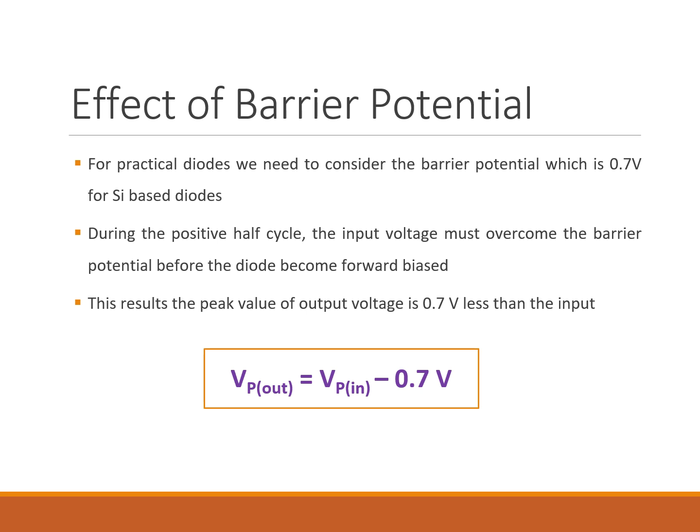And this matters because in low voltage circuits, that drop can be significant. If you're dealing with large voltage, 0.7 volts is not very much. But if you're dealing with low voltage circuits, 0.7 volts could definitely make the difference. If your input is only, let's say, 1 volt, you're losing 70% of it. So in a regulated DC supply, you have to design around this 0.7 volt drop. Always account for it, whether you're building a rectifier, a clipper, or a limiter, and we'll find out what those types of circuits are next. Always factor in that V sub F drop for your results, or else they're going to be off.